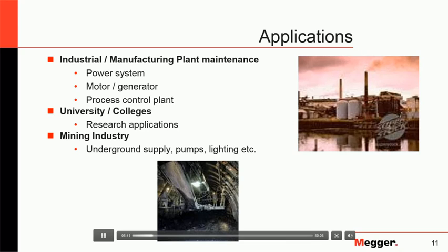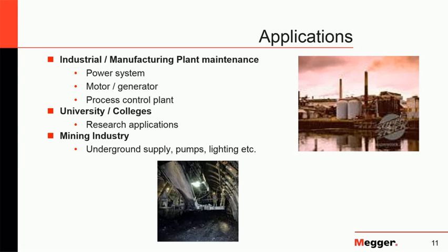In industries that consume vast amounts of electrical power, low resistance testing is a must. Let's say, for example, we have a bus in a substation carrying 12,000 amps of current. If our bus has a resistance of 1 micro-ohm, the power dissipated in that bus will be only 144 watts.